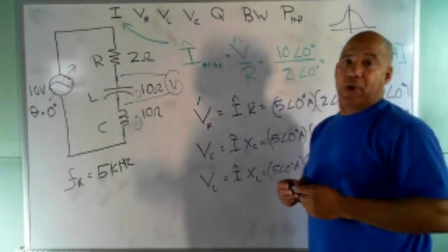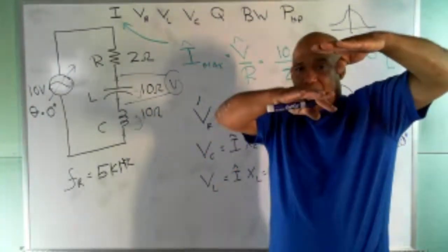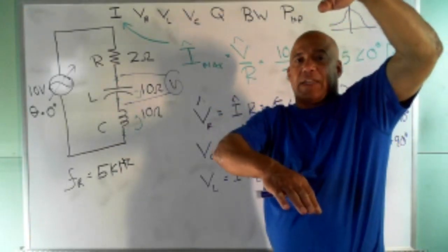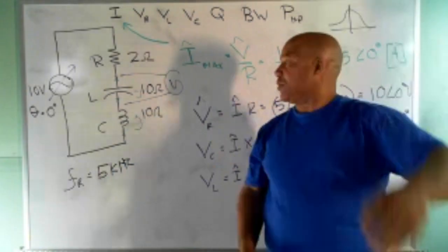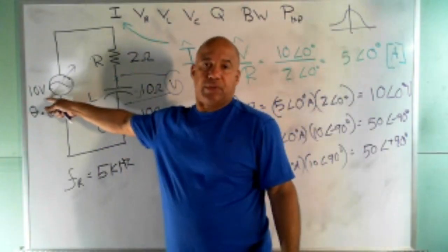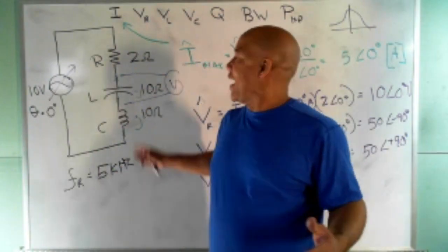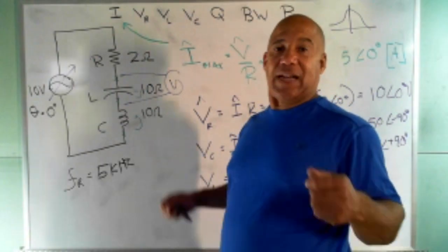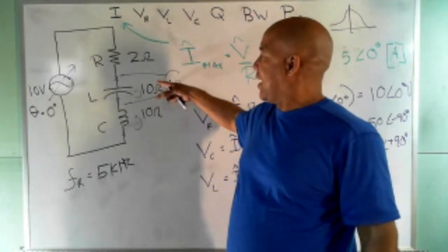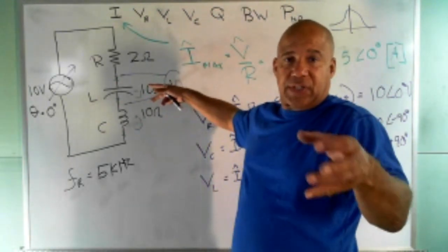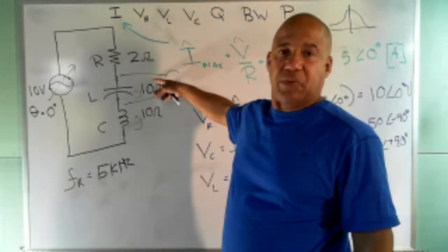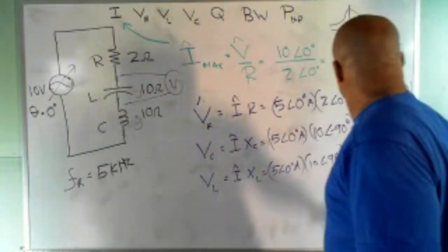What you would see is a sine wave, and the way you would know you're in resonance is the sine wave amplitude will get big. And resonance is the biggest it's going to be. If you go past resonance, it'll start to shrink again. So you got that amplitude across here and here, 5 times the source voltage. So at resonance, my reactive components are highly sensitive. If you're using this to pick up radio frequency, you tune to the station frequency, and you'd have a very, very high voltage for that particular radio station on your resonance circuit. 50 volts.